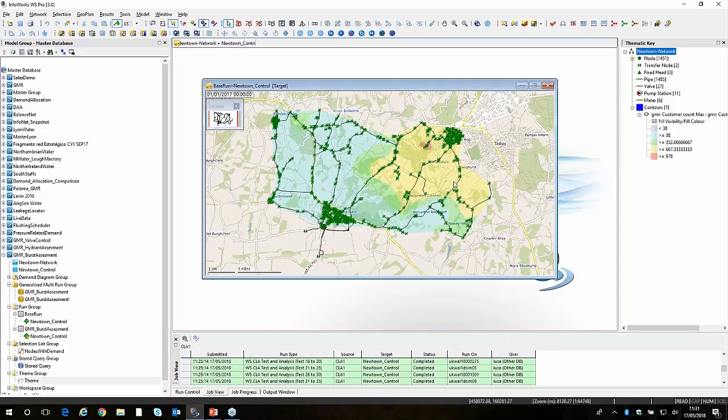So as you can see, in the critical link analysis, we were isolating a pipe and seeing the impact. In this specific example of a generalized multi-run, we are adding an additional flow, simulating a potential pipe burst on our system. And it is relevant because we know the number of properties affected. So we know that we need to pay attention not to have a pipe burst in this zone. Otherwise, we will end up with a lot of customers that will run out of water.